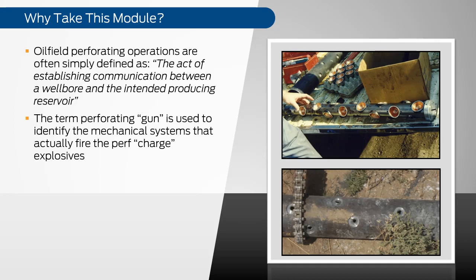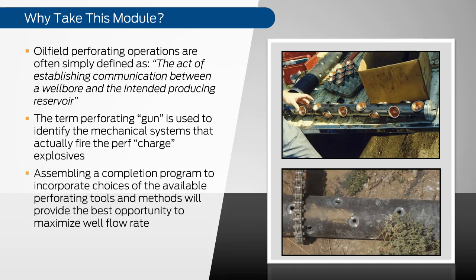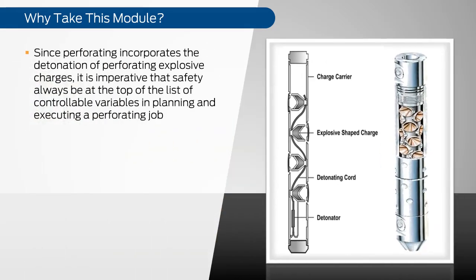For a completions engineer, assembling a completion program to incorporate choices of the available perforating tools and methods will provide the best opportunity to maximize well flow rate. Since perforating incorporates the detonation of perforating explosive charges, it is imperative that safety always be at the top of the list of controllable variables in planning and executing a perforating job.